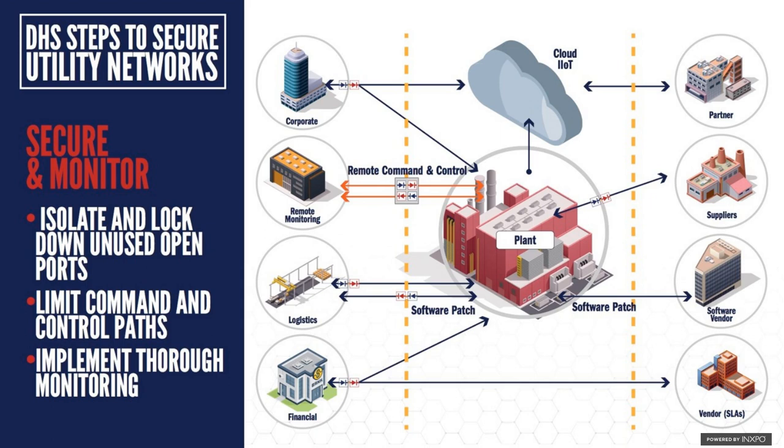The recommendation is to lock that down, close any unused ports, and limit the command and control connections, what's actually going to occur on there. Then you've got your intrusion detection systems and all the other threat mitigation and threat analysis resources that you can now apply to this connection. And let's be realistic, maybe there are three or four of these.